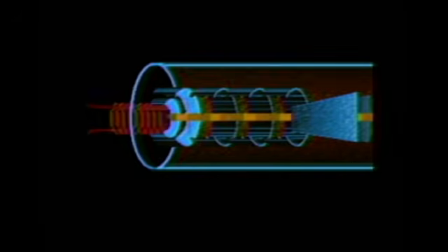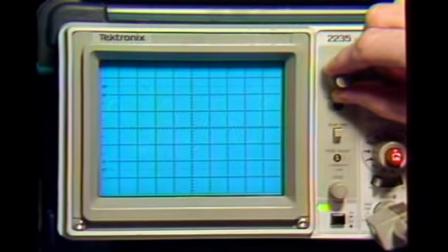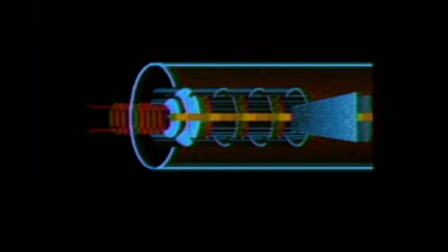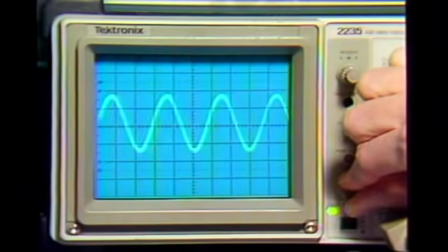As the electrons are attracted toward the first anode, they pass through the grid cup. The grid limits the number of electrons passing through the hole in the grid cup. Electron flow is controlled with the front panel intensity control. Now the focusing and accelerating anodes start shaping the electron flow into a narrow beam. Spot size is adjustable by using the focus control on the front panel.